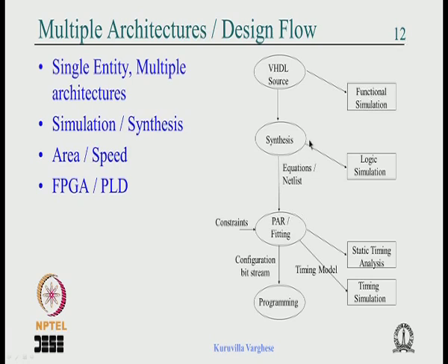At this point you can go for a logic simulation. What you simulated before was code, but here you are simulating a circuit which implements the equivalent functionality. Whatever is written in the code, the equivalent functionality in terms of the logic circuit is simulated here. Mind you, at this point there are no delays. Suppose you have an AND gate and you give the inputs.